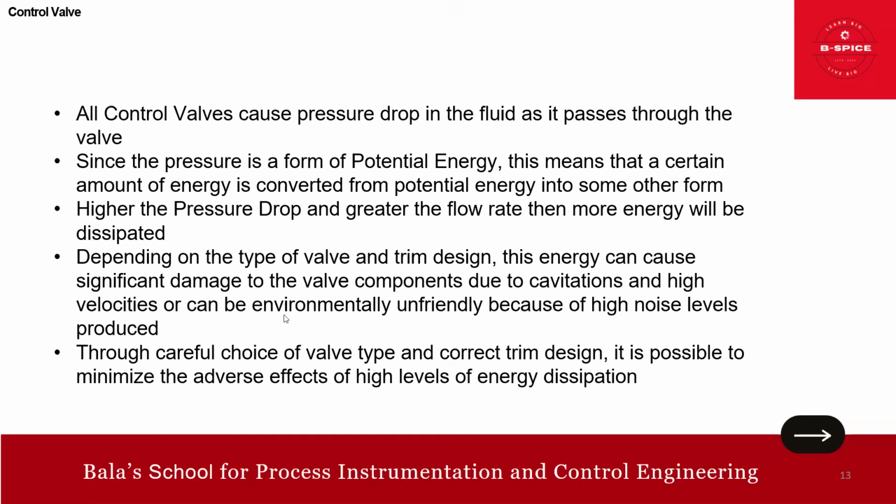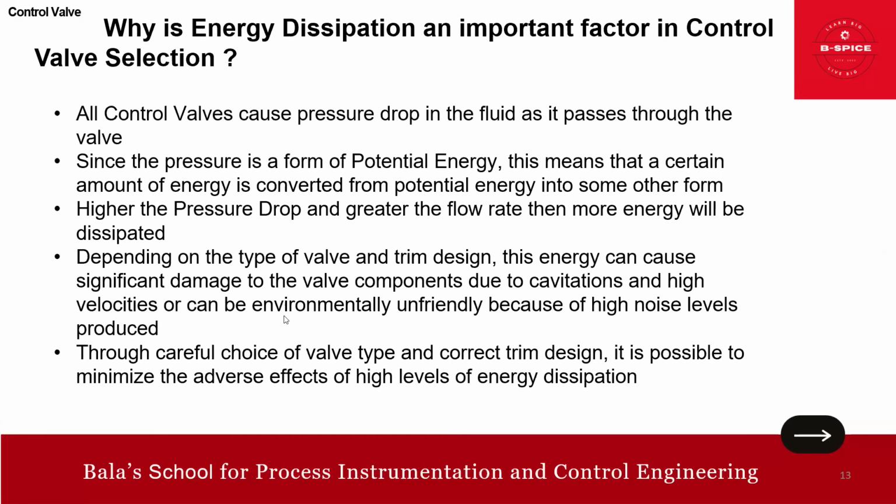Now, why is energy dissipation an important factor in control valve selection? Of course, very important. All control valves cause pressure drop in the fluid as it passes through the valve. This we all know, right? Since pressure is a form of potential energy, this means that a certain amount of energy is converted from potential energy into some other form.